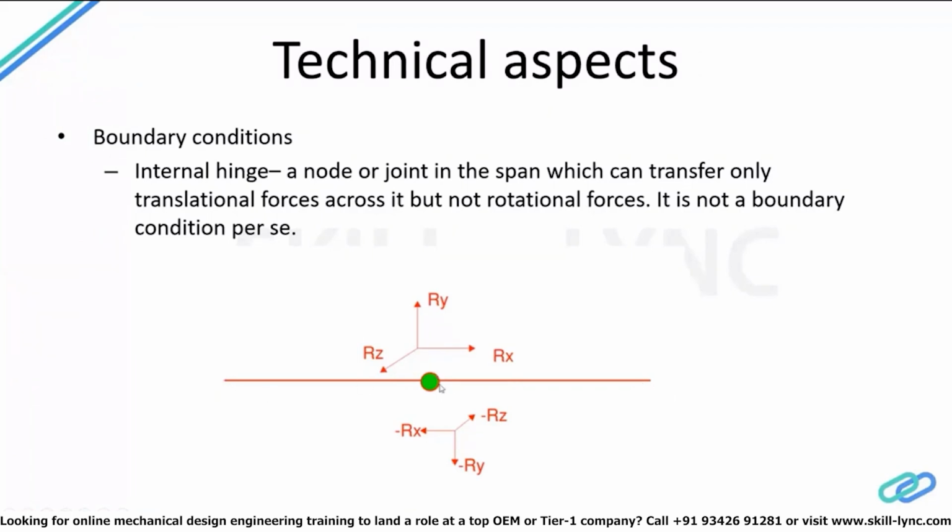is you would end up splicing that beam here. So if you have a splice connection here, that splice could be a shear type splice, or it could be a moment splice, wherein if it's a shear splice, that's more like an internal hinge, where it would just transfer shear across from one member to the other. But when it's a moment type splice, in that case, you also make sure there is continuity in moment as well. So these are a few possibilities that we have in terms of achieving the different degrees of freedom and the boundary conditions in a given structure.